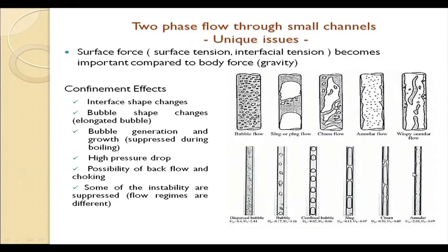And only at very high gas velocities do we get a situation where the gas is flowing at the center and the liquid is flowing as an annular layer. So, dispersed bubbly and annular flow regimes, which are inertia dominant flow regimes, are not very frequent in microchannels.